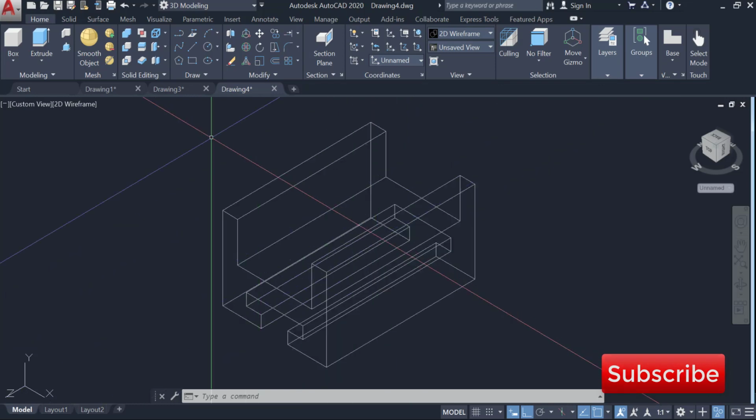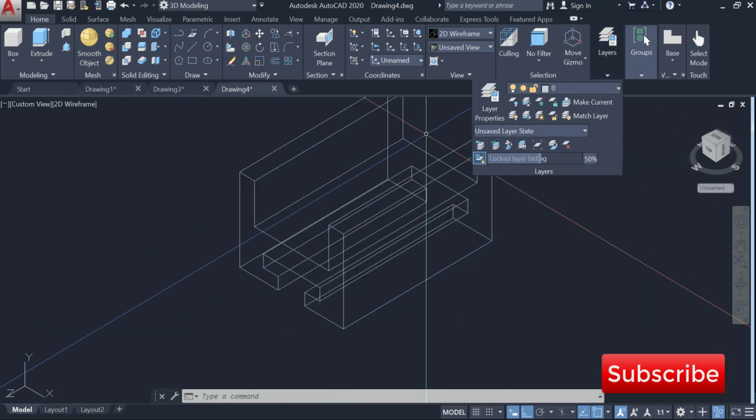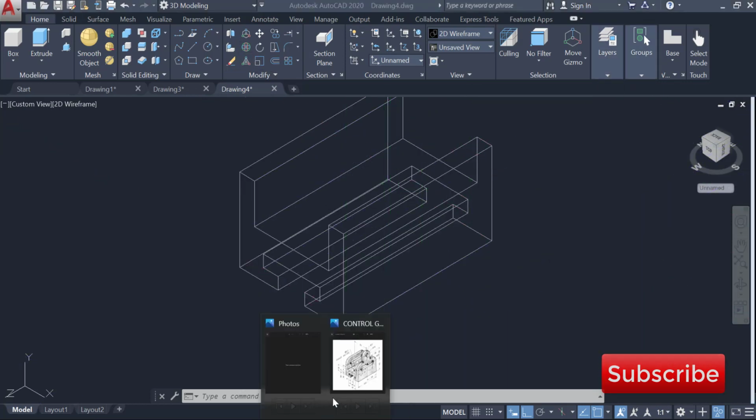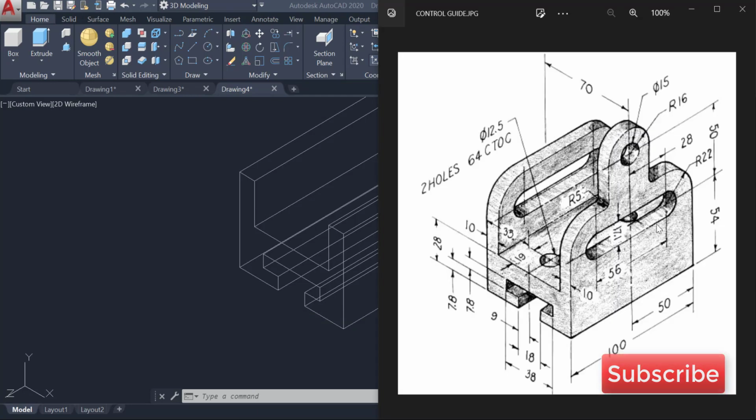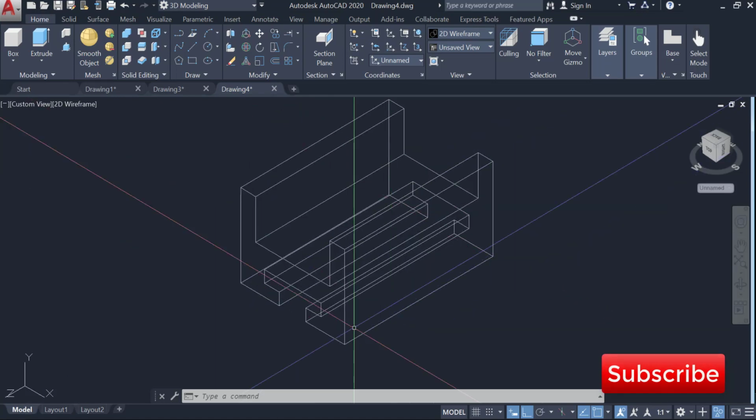Anyway, let's continue. So from here we need to draw a shape because currently we need to work out this slot. So we need to create a center line from here, which will be red. So we'll create a half line from here of length 28, and then we'll mirror it. So it'll be a length of 56. So we'll draw a small circle and a big circle, and also we'll copy this circle into here, and then we'll do some trimming, extrude, and then we'll get this shape. So let's do it. Let's put words into action.